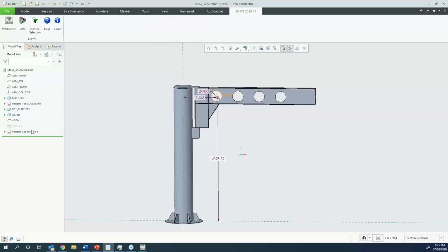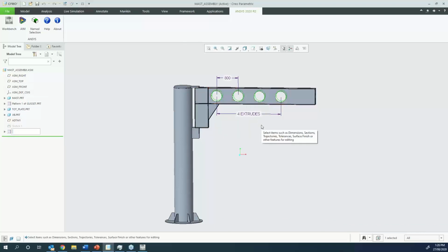So I'm controlling that. And over here, I'm controlling two different things. One is the hole pitch, so that's DS hole pitch, you can see that. And then this one here is the number of extrusions that we are having in our pattern, so essentially the number of copies of this. This is copied sequentially as many times as we want.